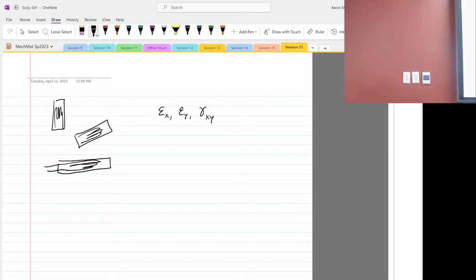It also gives epsilon z as 0. Since there's no in-plane shear strain, it would be epsilon x divided by 2. Epsilon x is all the way out on the right, and dividing that by 2 gives the radius of one circle.